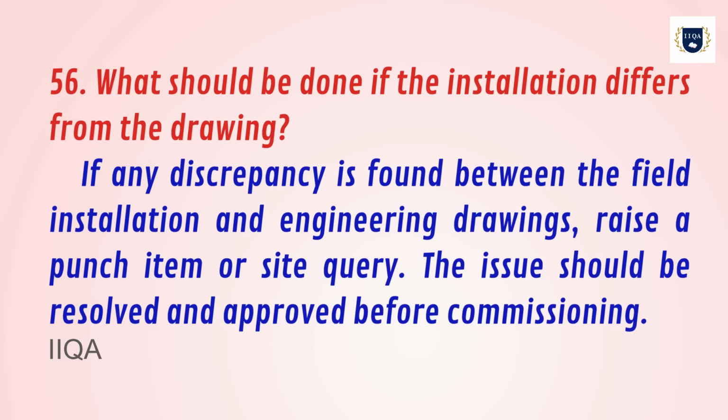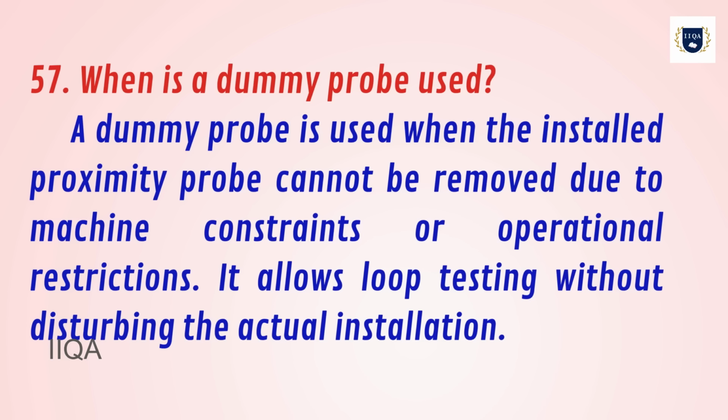56. What should be done if the installation differs from the drawing? If any discrepancy is found between the field installation and engineering drawings, raise a punch item or site query. The issue should be resolved and approved before commissioning.